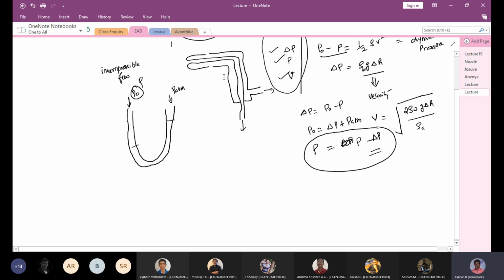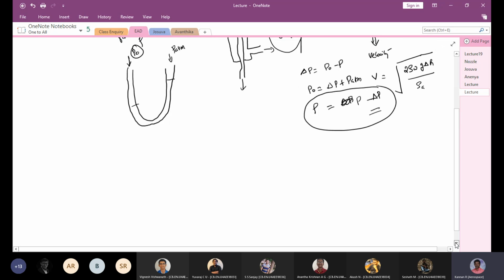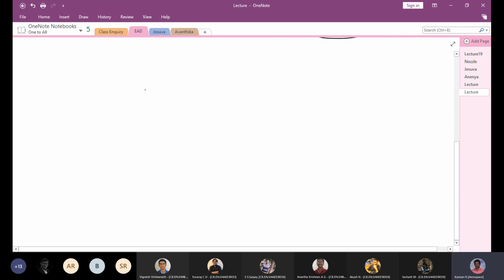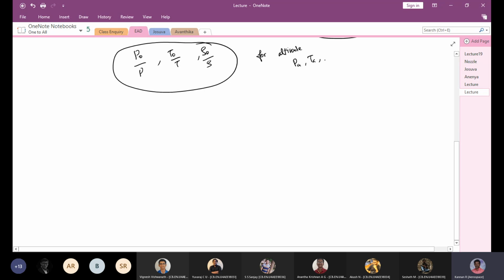In the same way, you need to know P naught by P, T naught by T, rho naught by rho. If they give you, for a particular altitude, PA, TA and rho A, you should be in a position to calculate your P naught, T naught, that is, your stagnation conditions.